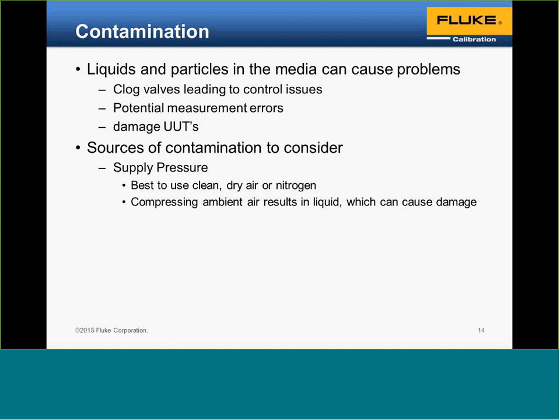Contaminated air can get into the system and cause damage. If the supply is contaminated with liquid, it can get into the pressure sensor and other components, cause corrosion, and cause valves to get clogged. So be careful of any contamination from your supply pressure.